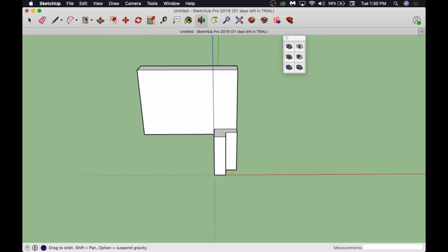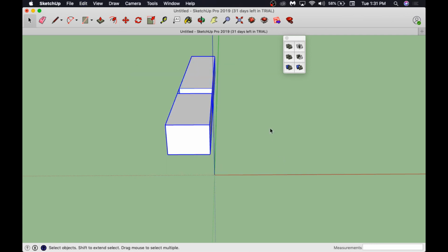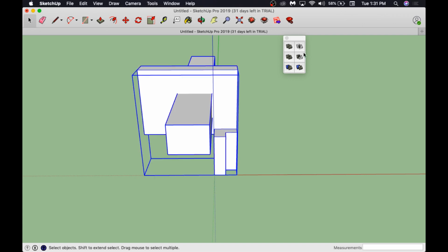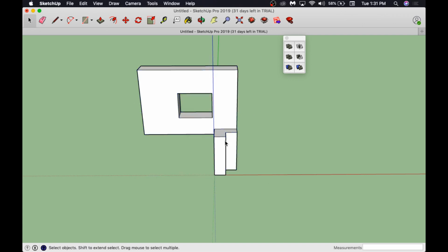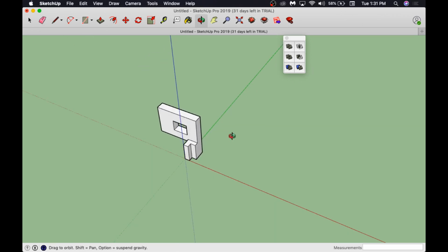If you want to make a hole in something, for example, not that you'll be doing that in this, you can draw that on the surface, and then you can grab this and extrude it. And because we're grouped, it's not sticking to anything, so that's nice. Triple click, Control G, this plus this with a subtraction. Oopsie. This plus this with a subtraction gives us a hole. Okay, so those are solid tools at their best. You just select the subtractor and then the subtractee, and then hit the button.